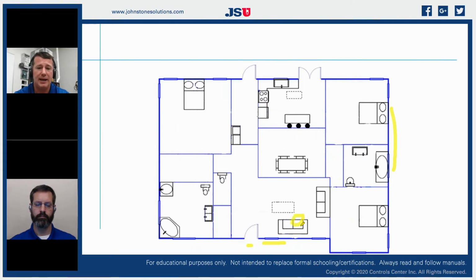We're going to be looking at occupants, because we don't always think about that, but as humans, we produce a lot of heat. So we have to look at how many occupants are in our facilities and what type of appliances are going to be in them. We have to look at how large a TV we have, because that television is using wattage and emitting heat as it's running. Also the computers in these facilities. There are lots of different things that add heat loads to our structure, and the construction of the material alone will affect our heat absorption and heat rejection. It is going to make a big difference in the amount of equipment that you can put into a facility.